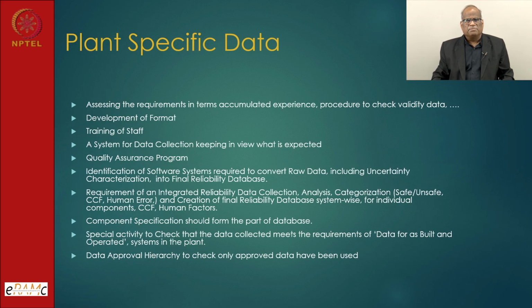Plant specific data, there are many points I have indicated here. We should first have a data collection format. Data should be collected, and we should be very particular about the common cause failure data and human failure data. And the component specification, if we take data from a generic source, to the extent possible we should do component specification matching of the data, so that even if it is not available from a plant source, we are trying our level best to get the correct data.